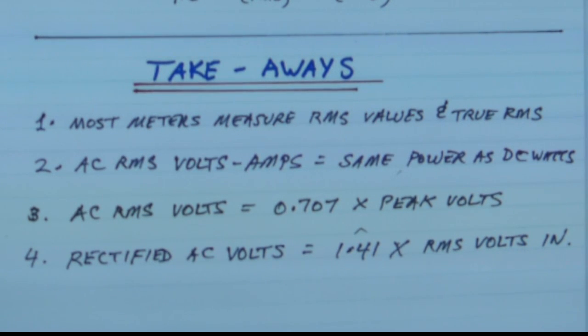What's true RMS? Well, say you don't have a sinusoidal waveform. Say you have a complex waveform, like, for example, in an audio voltmeter, you have a complicated waveform. Or say you have some kind of circuit where there's a triangular or a square waveform, or some other non-sinusoidal waveform.